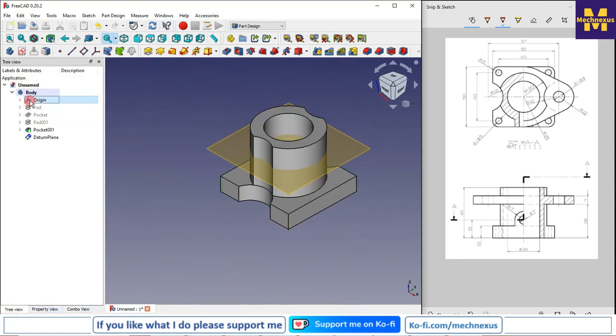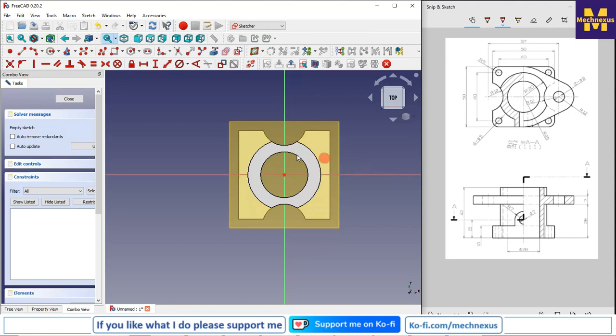Now I will turn off my origin plane. Now I will select my datum plane and create a sketch. Here, instead of making it in one sketch it will be complicated. So what we will do, we will first create a rectangular plate and then we will add this arc and this tangent line.